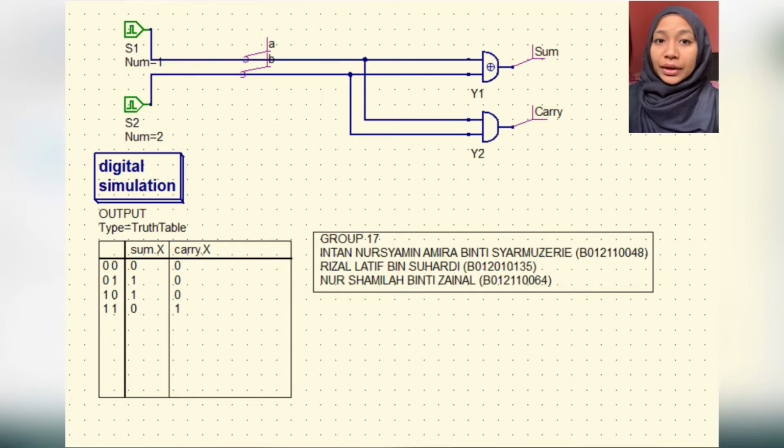If you observe the sum values in the truth table, it resembles an XOR gate. Similarly, the values for carry in the table resemble an AND gate. So, to properly implement a half-adder, you need two logic gates: an XOR gate for the sum output and an AND gate for the carry output. Half-adder is mainly used for addition of augend and addend of first-order binary numbers, for example, 1-bit binary numbers. We cannot add binary numbers of more than 1 bit as the half-adder cannot include the carry information from the previous sum.